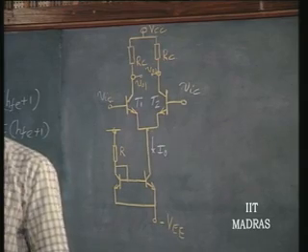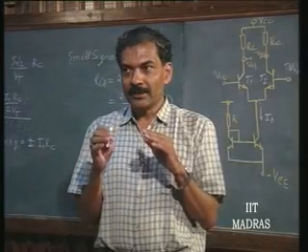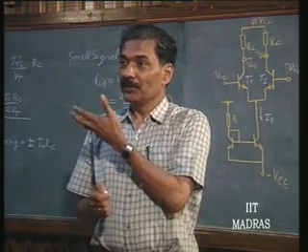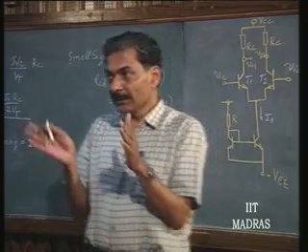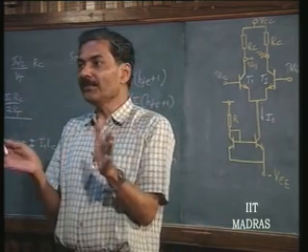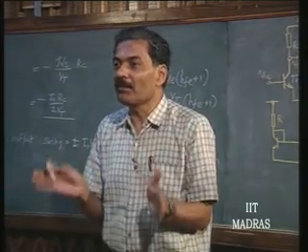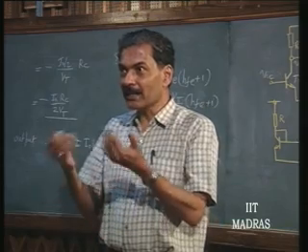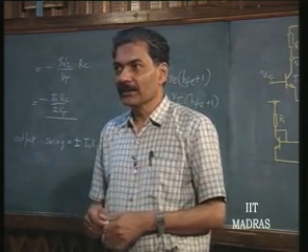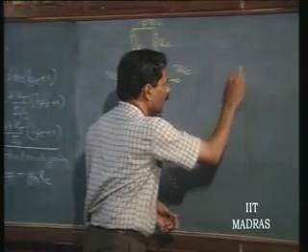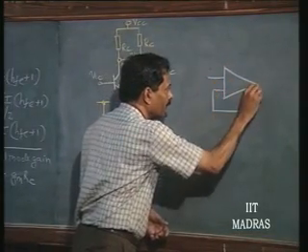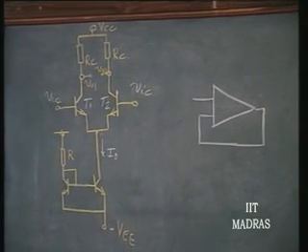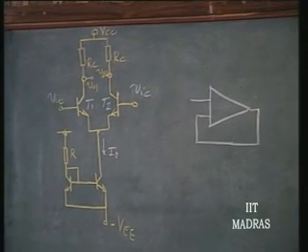Once again I want to clearly tell when exactly this situation arises in a troublesome manner, because you do not want to bring trouble unnecessarily. When this input stage is being used without feedback, you will not unnecessarily cause a common mode problem for yourself. You will always try to eliminate any problem. Where will it come without you asking for it? It is going to appear in a negative feedback situation. The worst case of common mode trouble occurs in a unity gain mode of operation. Let us see this.